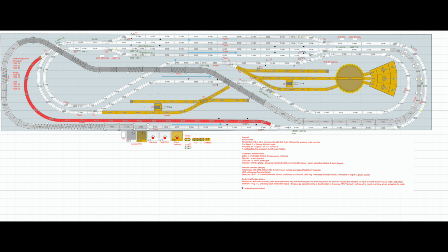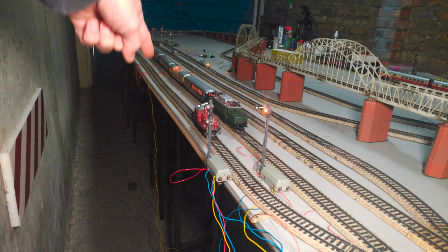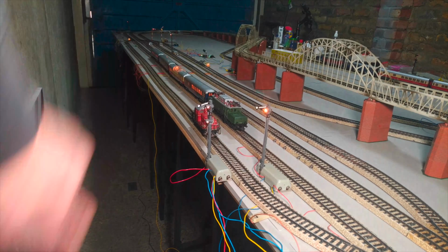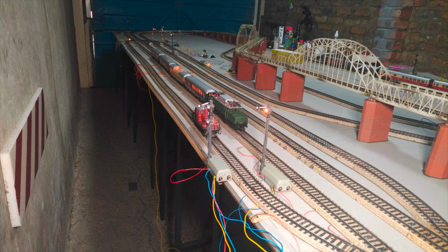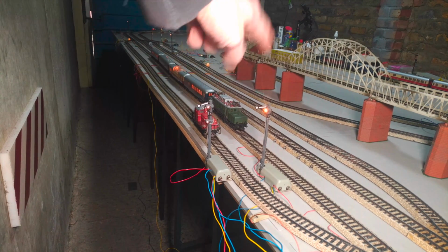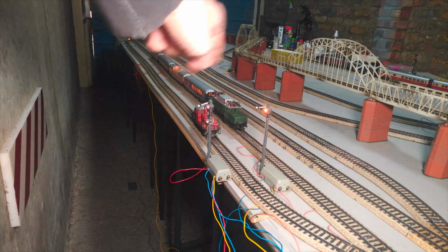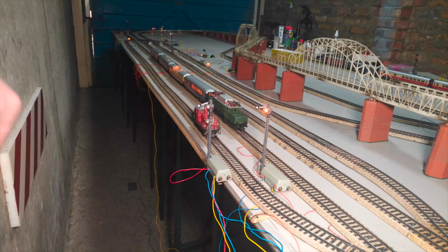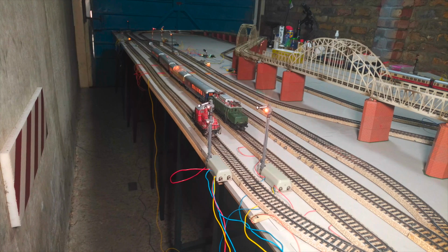I'll be working on the line I'm currently pointing to, and what I'm trying to achieve is to set up an automatic release mechanism to alternatively set one train waiting at one of the signals in motion. I'll also be integrating something to change over the turnout located at the entrance of the station so that trains always enter a vacant track.